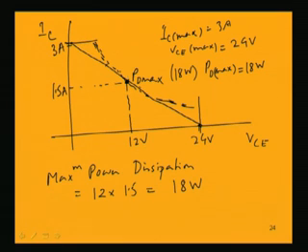And for different resistance value, of course, RL if it is changed, we will be having different power dissipation. So, your point of maximum power dissipation will vary and corresponding voltage and current will also vary. So, we will be having that hyperbola within which we should remain. The product of this current and voltage should give you a value below this power hyperbola, that is the safe operating region.